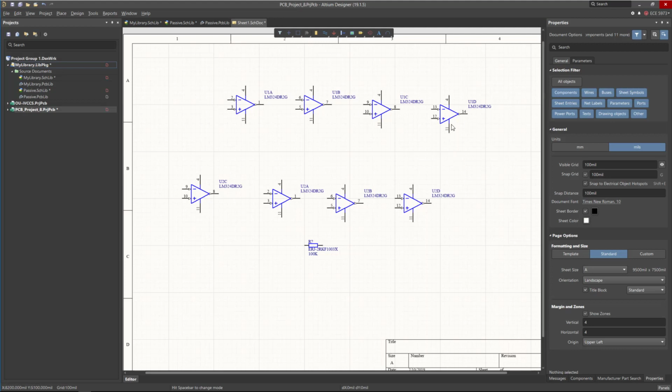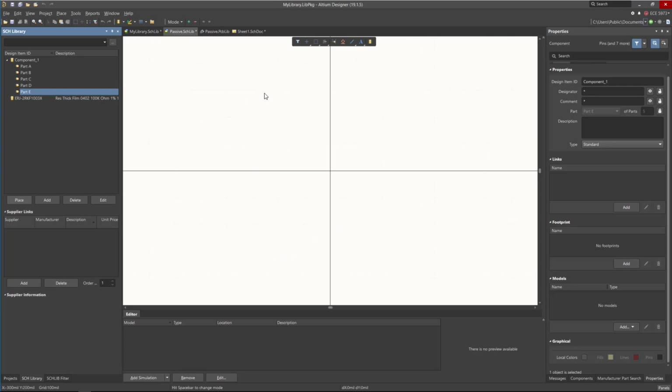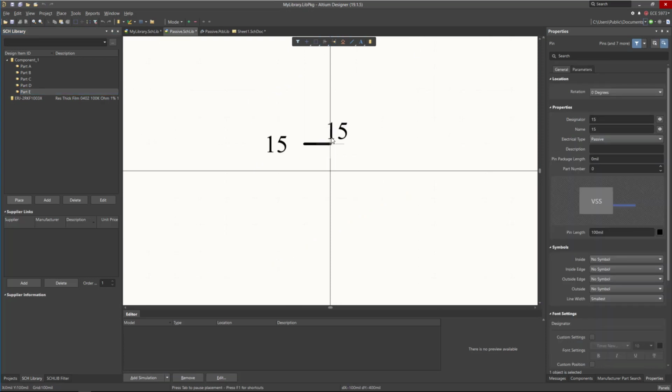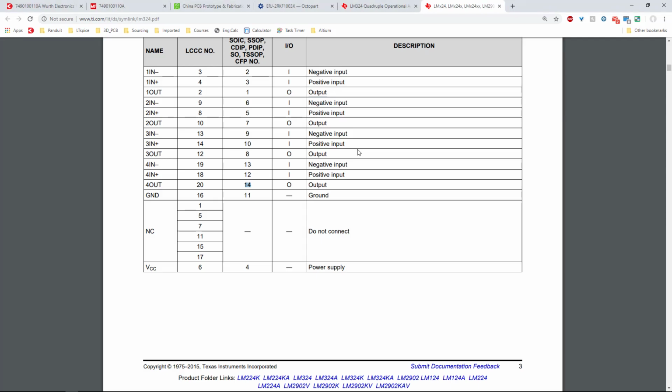It's just 2 pins. Why do you want to duplicate these? So what you can do is create a part, and this part is for the power. Now you can add the first pin like that. Remember, electrical property to the outside, and you can add another one from the bottom side like that. Now you need to hide the name, given that we need to change it, and we go back.